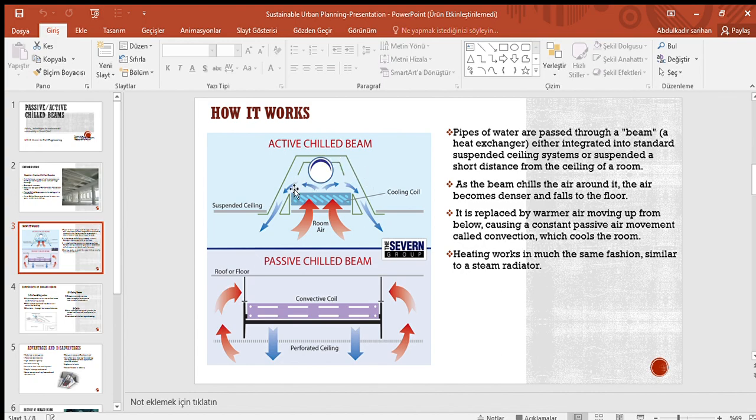When the air goes out from these nozzles, a low pressure forms in this area, and with this low pressure, the air inside the room comes here and touches the cooling coil. It goes up and again goes out from these nozzles into the room. So in each step the air mixes and gets cooler or hotter, depending on what we want.